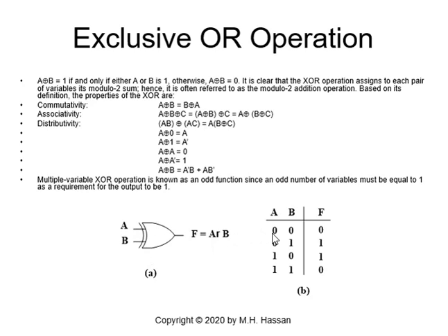It's in A. This is a typo here, A exclusive OR B. And the truth table is what we get. 0, 0, F will be 0. The input 0, 1, F will be 1. If the inputs are 1 and 0, F will be 1. Inputs are both 1s, 1 and 1, and the output F will be 0.